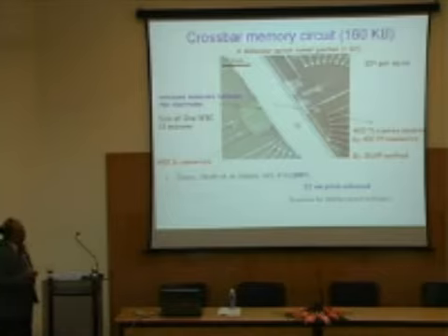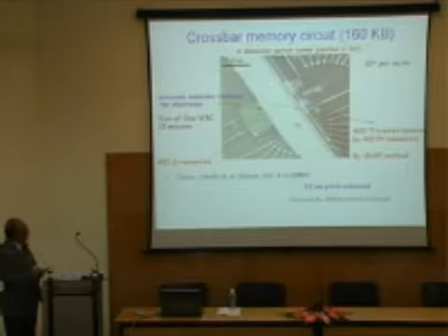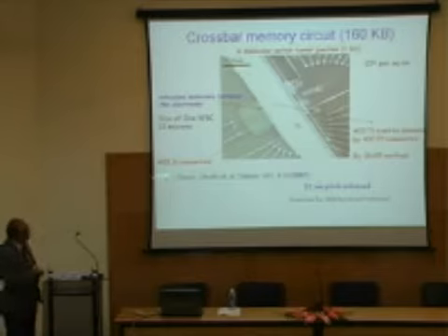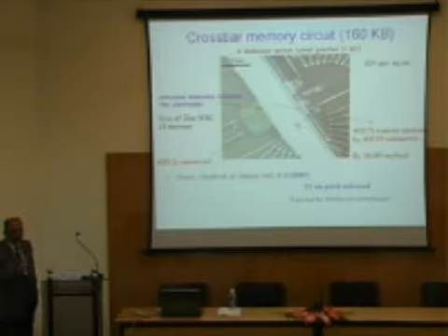So, there are around 400 silicon nanowires in this region, and this is of the size of one blood cell. So, you can imagine how small it is. It is the size of one white blood cell, around 13 microns, and it has got 400 silicon nanowires. The top electrode is going like this, and that has got 400 titanium nanowires, which is covered by platinum. So, the titanium wires are covered by platinum, and it has been grown by the same SNAP method, right.